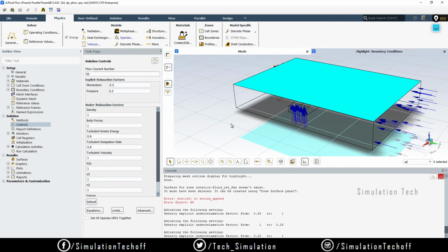There is no relaxation factor involved in the convergence. That means it may make your convergence process too complicated. So if I give a factor of 50 or 100, some relaxation may be done in the convergence process, right? Some assumptions may be made, to make the problem easier to solve. So I'll give the factor of 50.